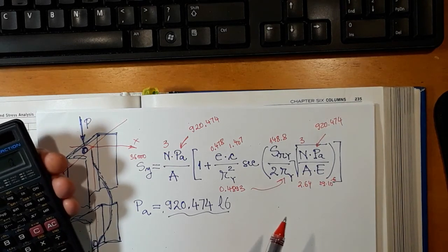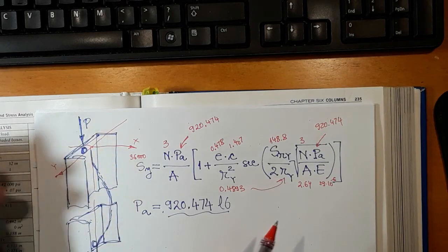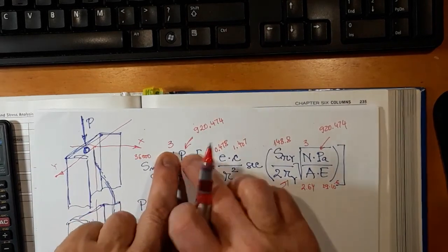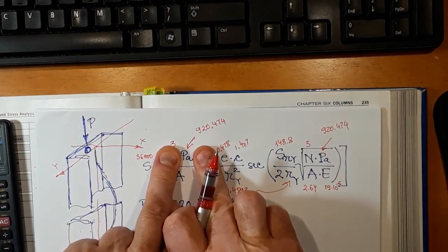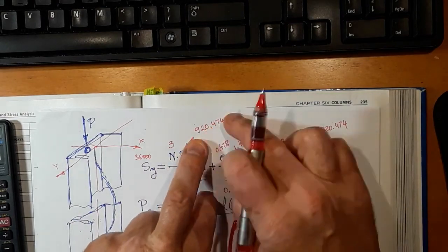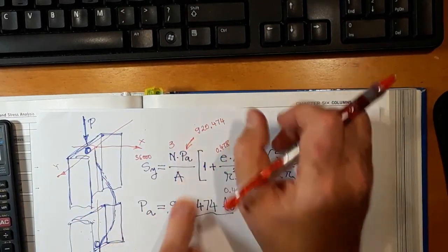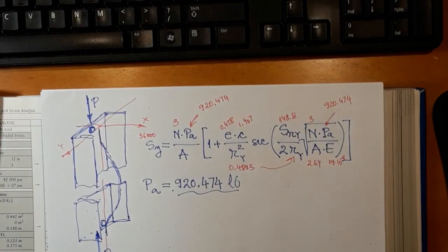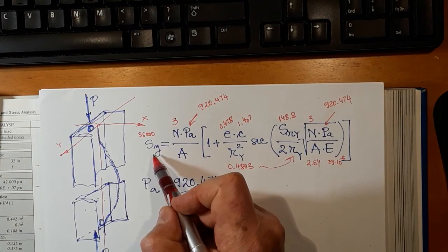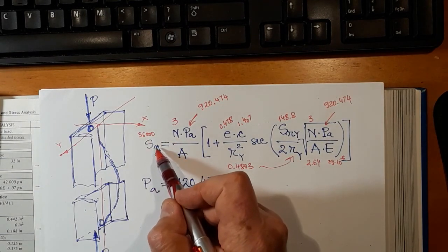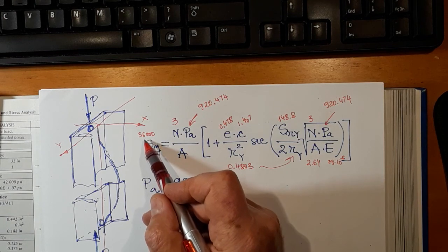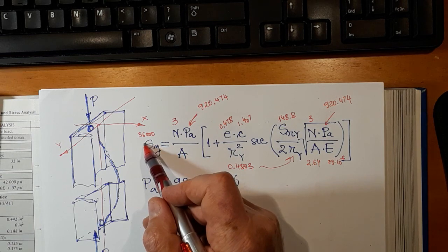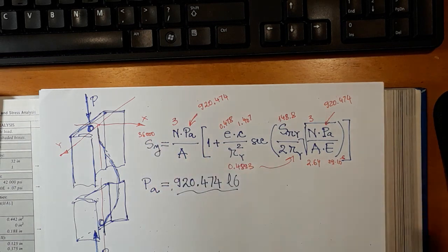Anyway, it's 10 p.m. where I'm recording. Feel free to implement this in Excel. Have a cell that is labeled PA, and you manipulate it, or rather try my value and see if, implemented in equation 615, it gets you SY, the required yield strength, very close to 36,000 PSI.